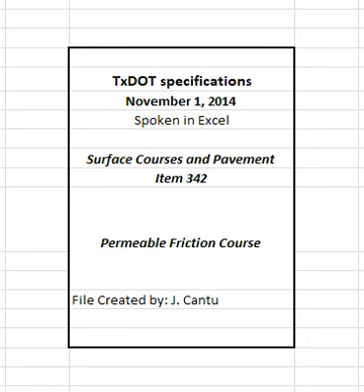The engineer may allow the contractor to use an alternate to the 3/8 inch or 1/2 inch screen to fractionate the RAP. Do not use department or contractor-owned RAP contaminated with dirt or other objectionable materials. Do not intermingle contractor-owned RAP stockpiles with department-owned RAP stockpiles. Remove unused contractor-owned RAP material from the project site upon completion of the project. Return unused department-owned RAP to the designated stockpile location.